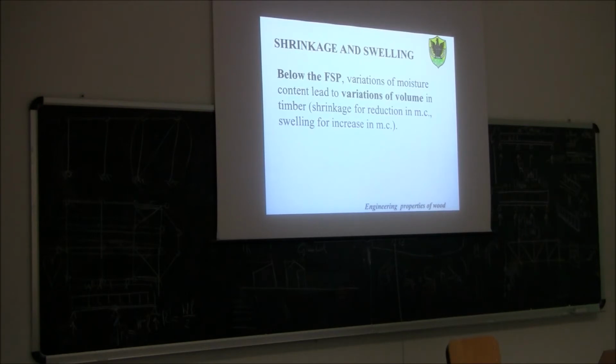This dimensional variation, unfortunately, does not take place without eigenstresses, which means self-stresses. Once the section shrinks, we will also have eigenstresses within the cross-section, and some of those stresses may become larger than the strength of wood. Particularly if we talk about tensile strength perpendicular to the grain.